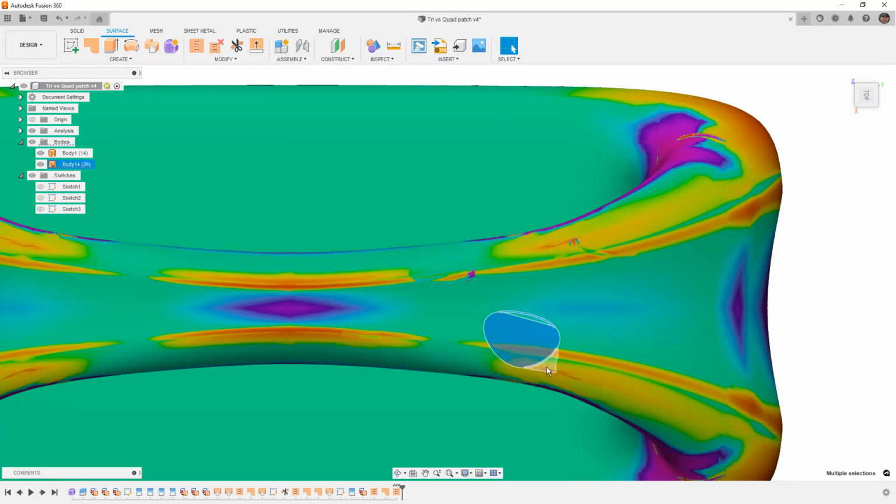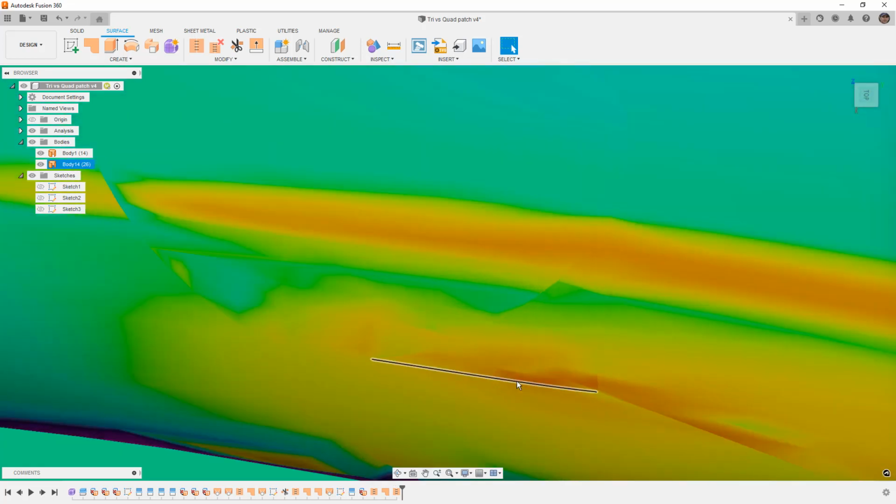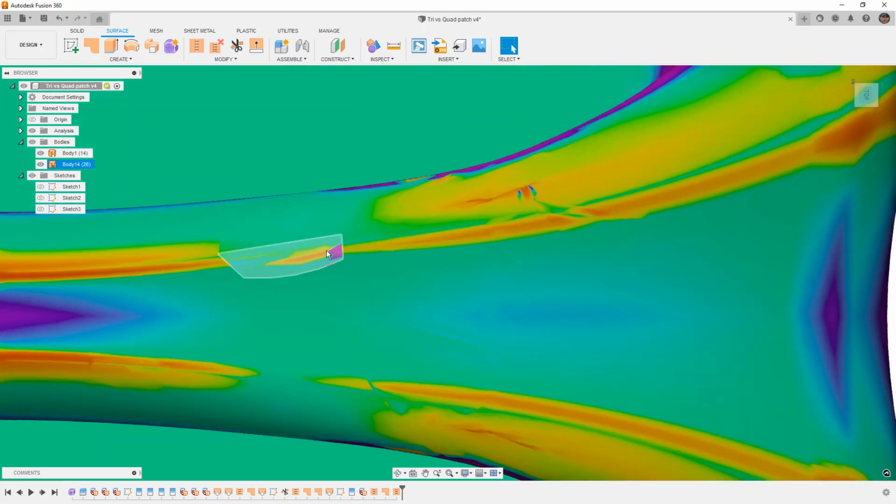This one that had sort of a curvature continuous cutaway did pretty well, but we did still have to patch those corners, which have their own inherent problems. Once again, that patch is giving sort of equal weight to everything, which means that anything that we have here that's green and red and yellow, it's all going to have influence. The next one that was sort of problematic was the one that had multiple sides. Now, again, probably the best solution is to cut away a little bit more surface, make it a rectangular cut, and then just do a loft from the starting profile to the ending profile.